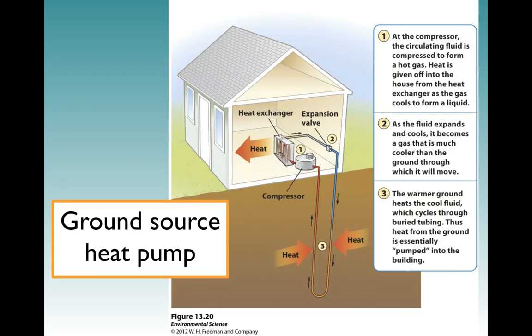Individuals can install a form of geothermal energy. It's called a ground source heat pump, so it's not the same. But effectively, what's happening with these is a heat exchanger where there's a heat differential below the surface of the Earth. The crust is warmer generally in some places, certainly during the winter months, significantly warmer than the air temperature at the surface. So you can have this set up installed. In some places, it can be a very cost-effective way of providing heat for the house, and then alternately, possibly cooling during the hot part of the summer.